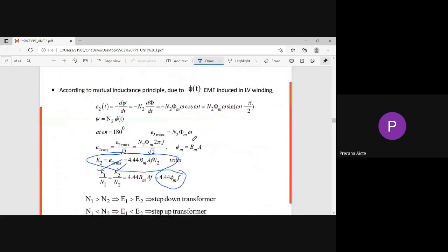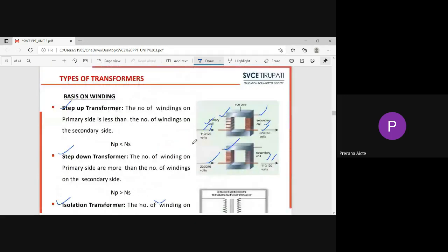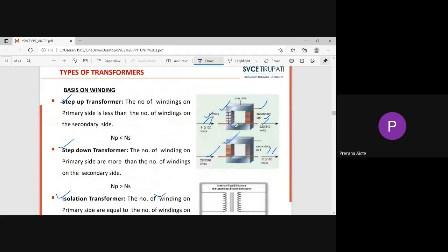For example, when flux flows through the core of the transformer, this flux is also linked with the primary and secondary windings, and EMF will be induced. That induced EMF is E1 and E2, our required induced EMF. In addition to this, the flux also links with the core of the transformer, and EMF will be induced. Your core has a closed path, so eddy currents are developed in the transformer core. For that, some amount of current is drawn from the supply mains.